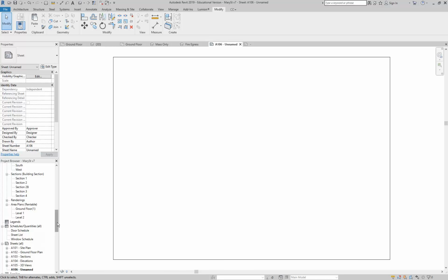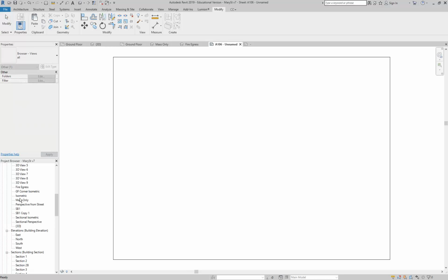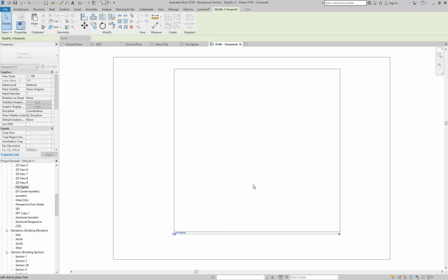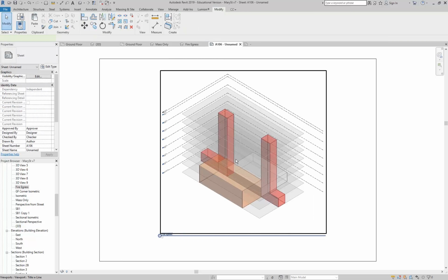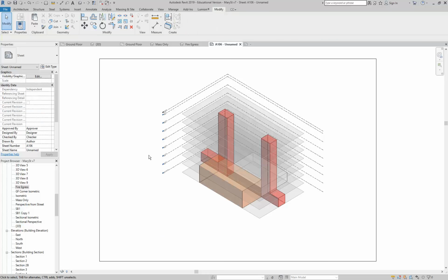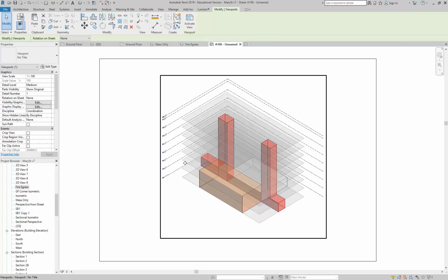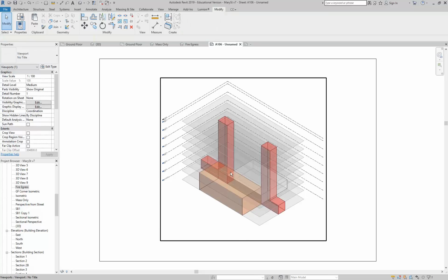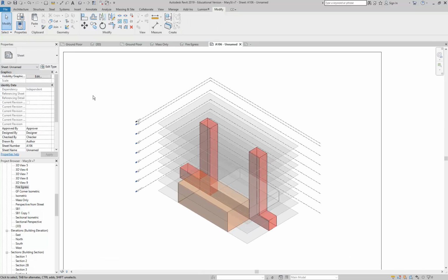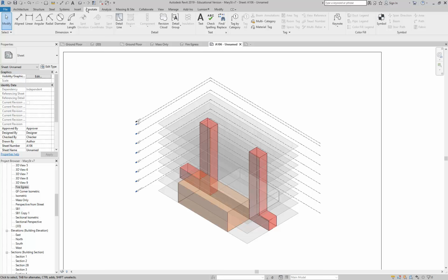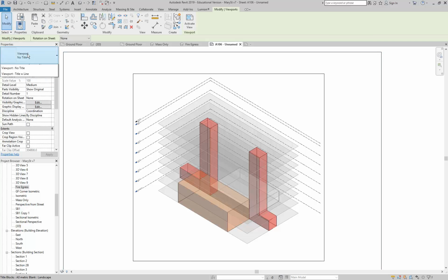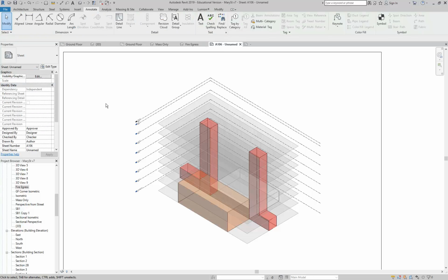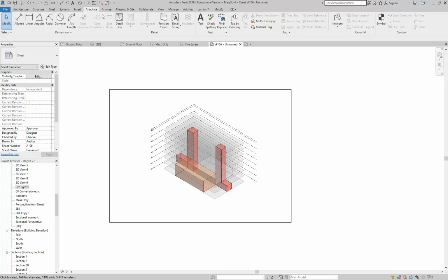Okay, so I'm going to put the fire egress view onto that page and turn the title off because we don't want any unnecessary annotation. We do most of the layout and presentation work in InDesign, of course, but where Revit's brilliant is that you can use detail lines, just setting it to title, no line, no title, viewport, no title. So, it's a brilliant option, and then that way you get a nice clean view.